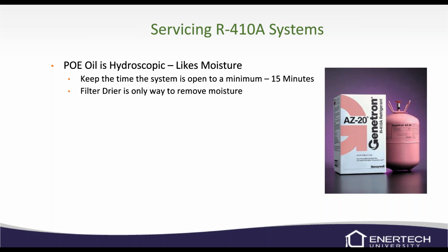So when you're servicing a system, make sure that you don't cut the system open and then go, well, I got to go get a filter dryer from the supply house, and while I'm at it, I'm going to go ahead and grab lunch, and I'll be back this afternoon. Don't leave that system open because it'll start pulling in moisture, and it'll get trapped in your system. So try to keep the system open at a minimum. Never unbraze a component from the system. Always cut it out of the system.